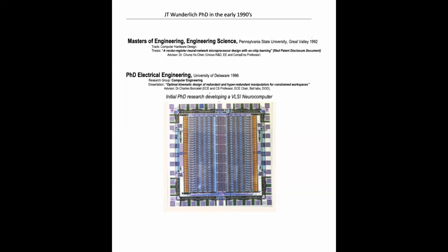The second processor, neural computer I designed and built, was based on the theory of a professor I had, which was to build chips based on the biological function, the electrochemical response, the firing of neurons in the brain, and the transient output voltage that comes out of the neuron after it fires, and to modulate that in different ways, and to change the dendritic tree that feeds into it, presumably to control learning later on.